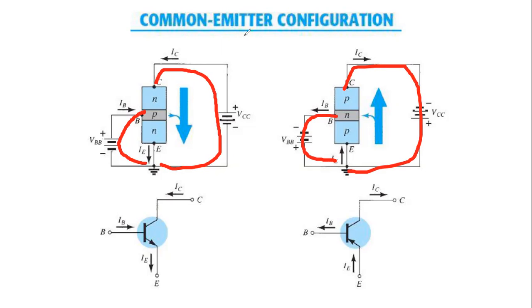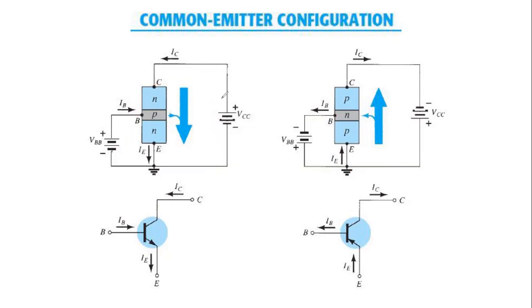And we also know that to operate the transistor in the amplifier region, we know that in the transistor there are two diodes available. So we need to make the emitter-base junction forward biased, and we need to make the base-collector junction reverse biased, isn't it?